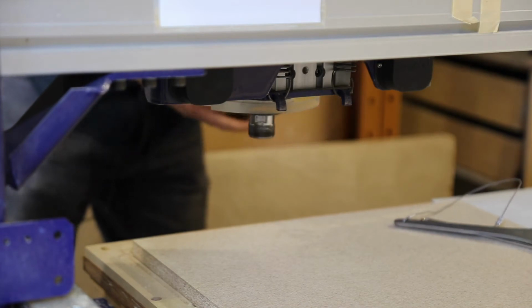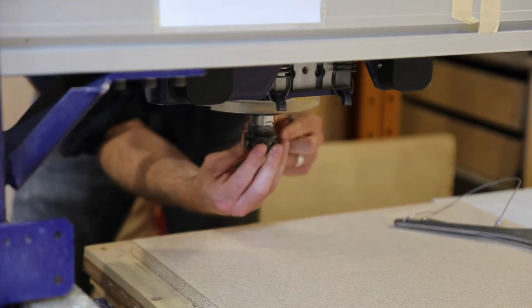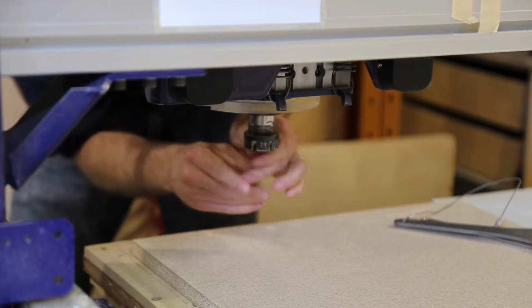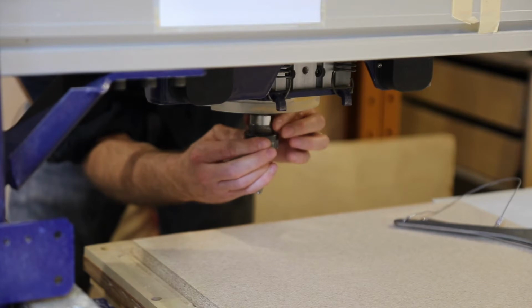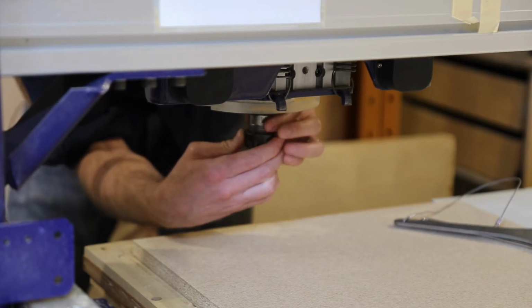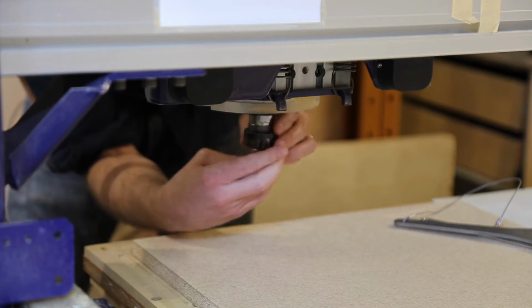For all cuts, you must use a 1/2 inch diameter bit unless you have a very good reason to use a different bit. Circumstances requiring a different bit could include holes smaller than 1/2 inch in diameter, interior corners that need a smaller radius than 1/4 inch, or cuts in 3 dimensions.